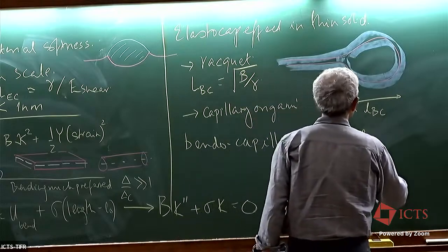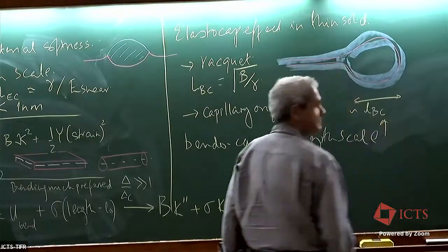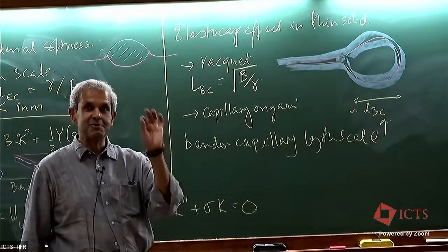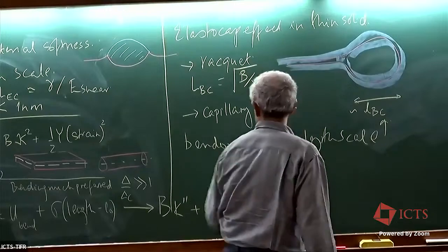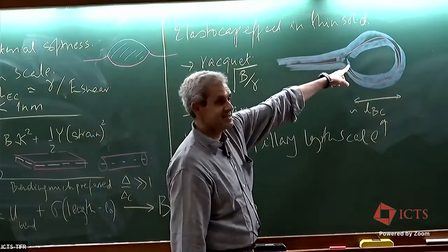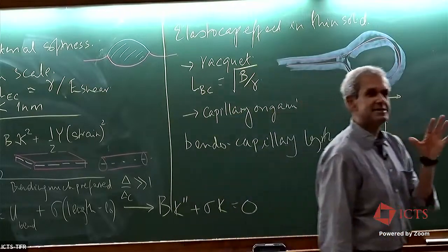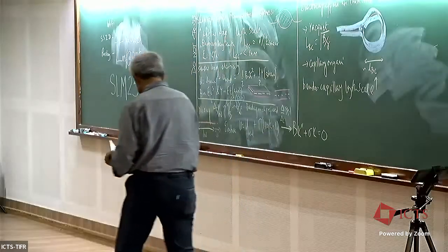And that sort of gets this problem correct. That's this. That more or less captures this problem. If you want to capture this problem perfectly correctly, then you will treat this as an elastica exactly like this. You will solve this equation with the right boundary conditions at the neck, and you'll get the shape perfectly. I think we said yesterday, I think I had it on one of my slides, you get a 90% correct answer this way. 90% is all I strive for.